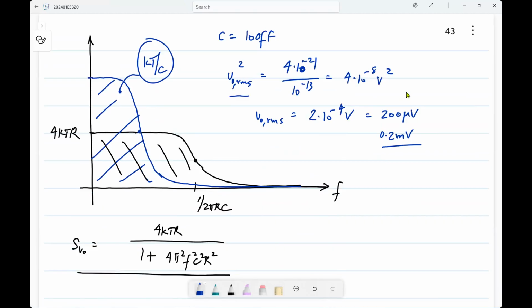Power dissipation of what? This has got nothing. This is only noise, right? There is no signal here. If you apply a signal, it depends on the signal. Of the noise, yes, only the noise. The variance of the output doesn't depend on the resistor value. But if you are talking about power dissipation in the resistor, that depends on the signal that you apply to the filter, right?